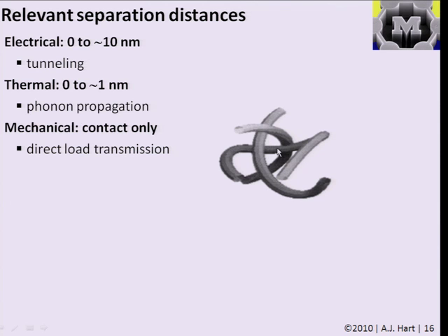In the case of electrical transport, certainly if you have good contact and/or bonding between the structures, then you're going to have better electrical transport than when there is a physical gap between them. But due to the ability of electrons to tunnel, essentially jump across a small gap, the same phenomenon as we know from scanning tunneling microscopy, in a gap of approximately up to 10 nanometers, you can get electrical transport across a gap if you have a sufficient bias voltage across your network.